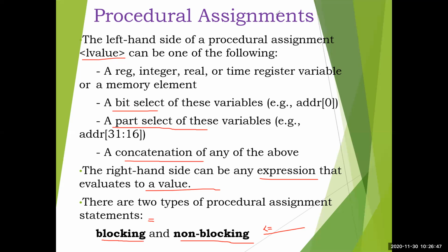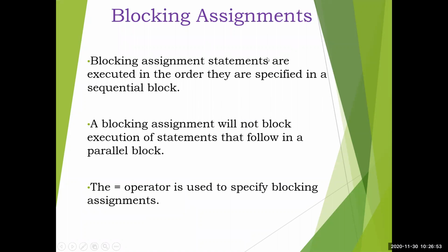First we'll consider the blocking assignments. Blocking assignment statements are executed in the order they are specified in a sequential block. The sequential and parallel block topic we'll learn next. In a sequential block you have a begin and end, and whatever statements you have written inside it will be executed step by step, one after another. That is the order.